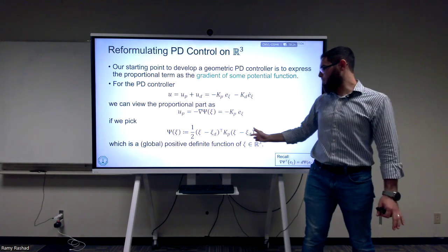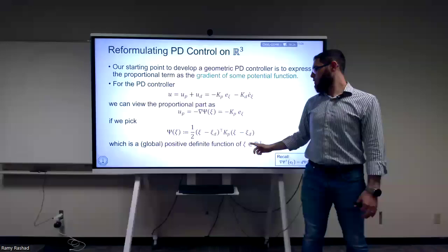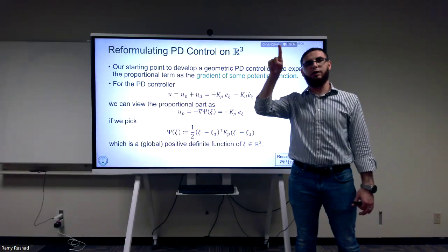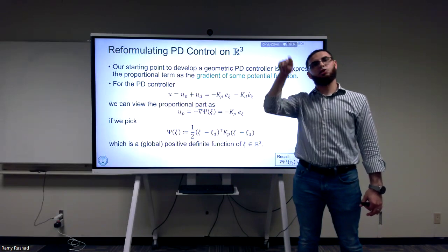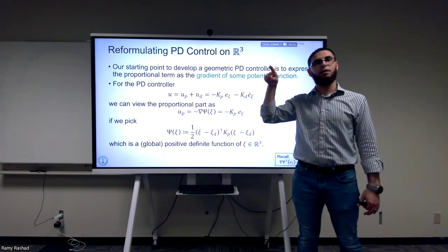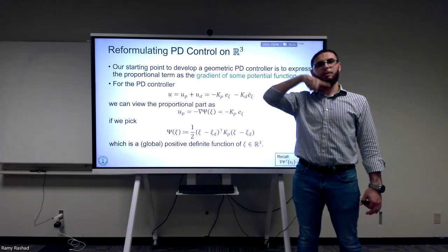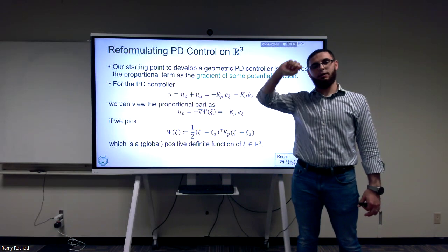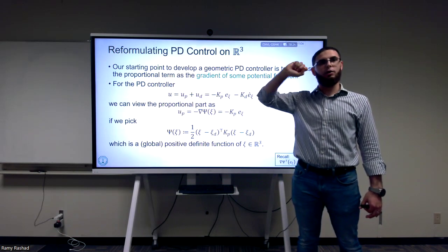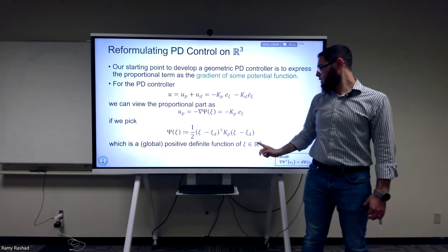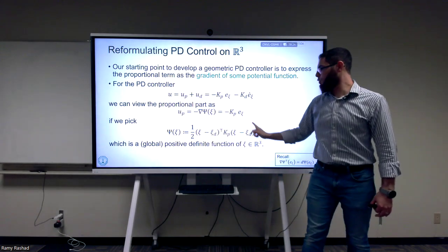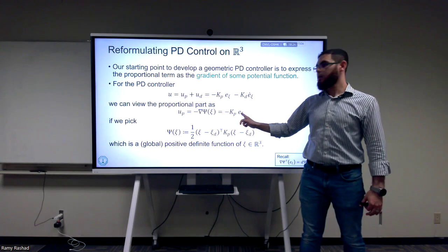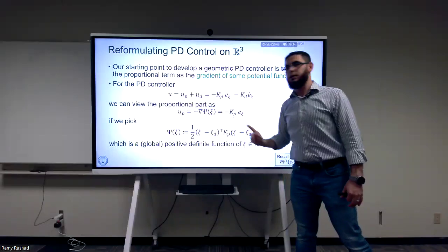Partial derivative, right? What's the partial derivative of this guy? This is equivalent to half m x squared or half k x squared. So we take the 2, multiply by the half, and then you reduce the order of the 2 to be 1, so you get in the end kx. So the gradient of this is equal to k of psi minus psi d, which is the error. And then I multiply it by a negative, and this is the kp.